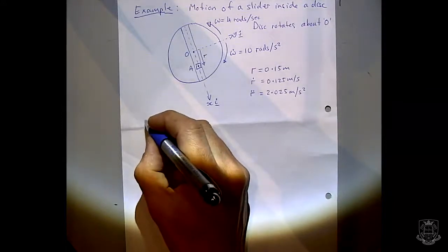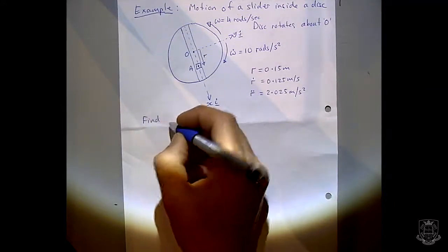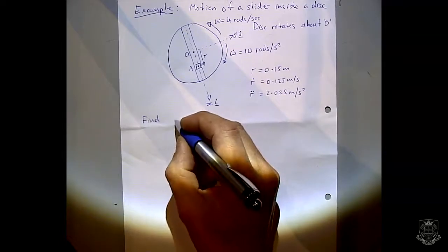And they're all given as scalar quantities, so they don't have the lines underneath them, because up to now we haven't really defined the vectors, we're just defining the problem and where the axes lie. Of course, we can turn them into vectors by multiplying those scalar quantities by i, j, and k as appropriate, can't we? But for now they're given as scalar values. So the question asks you to find the absolute velocity and acceleration of the slider at A.